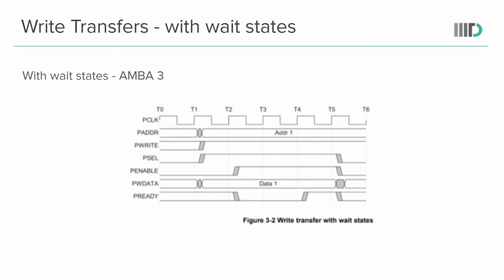Like the previously seen write transfer, this type of transfer differs as the number of cycles for a transaction to take place is longer. The reason for this is that sometimes APB slaves require more cycles to send the data. That can be due to some peripheral needing more time to respond to a particular prompt.